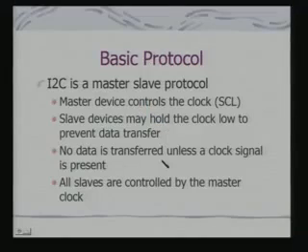So you have to put pull-up resistors, connecting these interface lines to the actual supply high voltage so that they can become operational. Since it's wired AND, the normal state would be high. When there is no transmission, it will be high, and if one of these slaves pulls things down, it will be low across the bus.